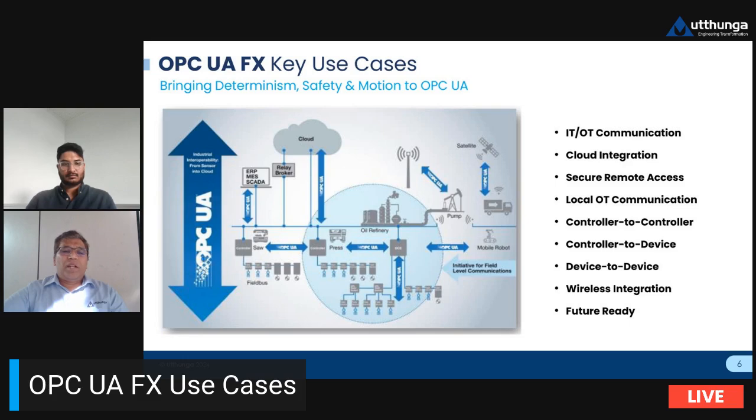Even some of the cloud infrastructures that are available have built-in OPC UA PubSub modules. So, for example, Azure has built-in OPC UA PubSub modules with which you can directly subscribe to data from any of the controllers that has OPC UA PubSub in it.